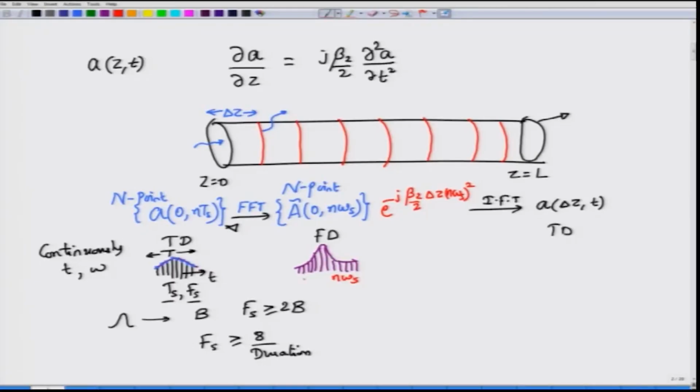In other words, you have the frequency array here, and once you have the frequency array or the frequency resolution, then you find out those particular frequencies and put that frequency here, and that is where the change is. So, if you initially take the carrier e power j omega 0 t, then the actual frequency that you are looking at will be the deviation frequency. But as long as you are working in the baseband, do not worry about it.